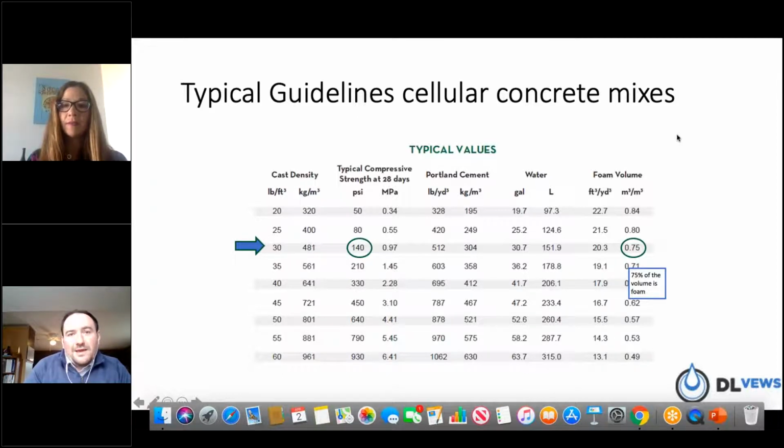Yeah, so the weight of water being 62.4 pounds per cubic foot, if you use a grout, whether it be flowable fill or cellular, that's, let's say, 70 or 75 pounds per cubic foot, you can usually succeed in that fashion.